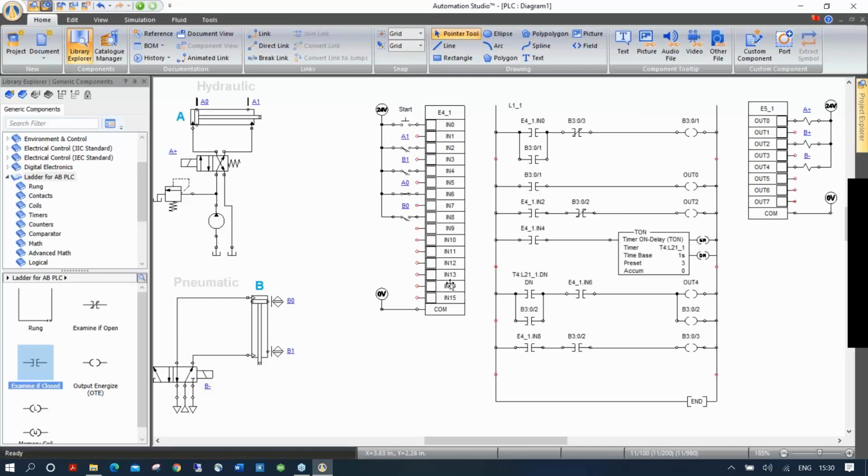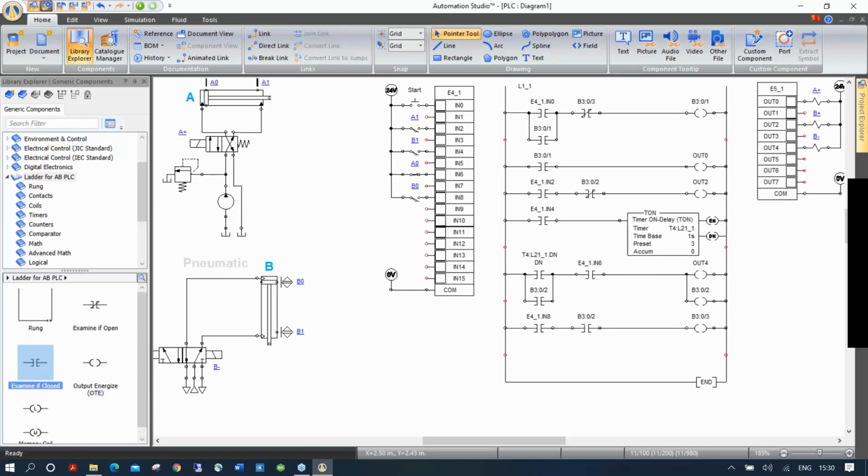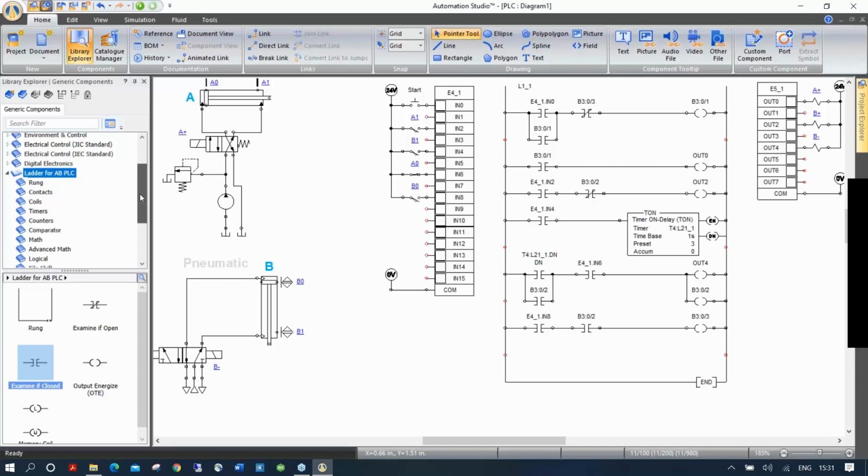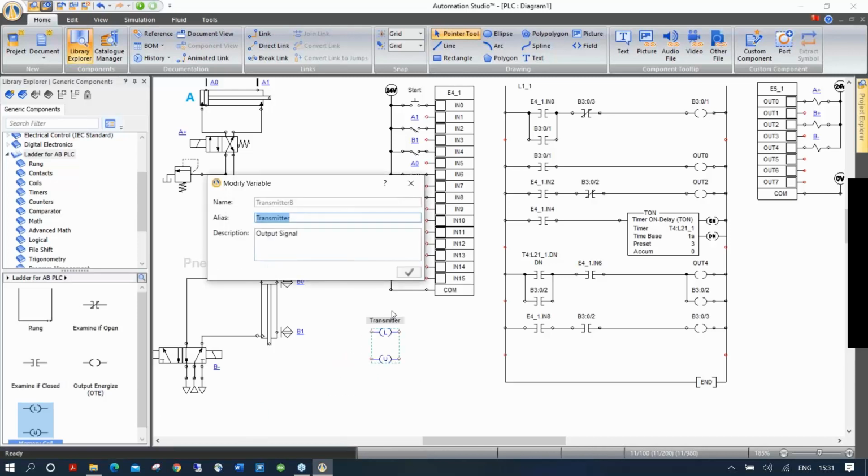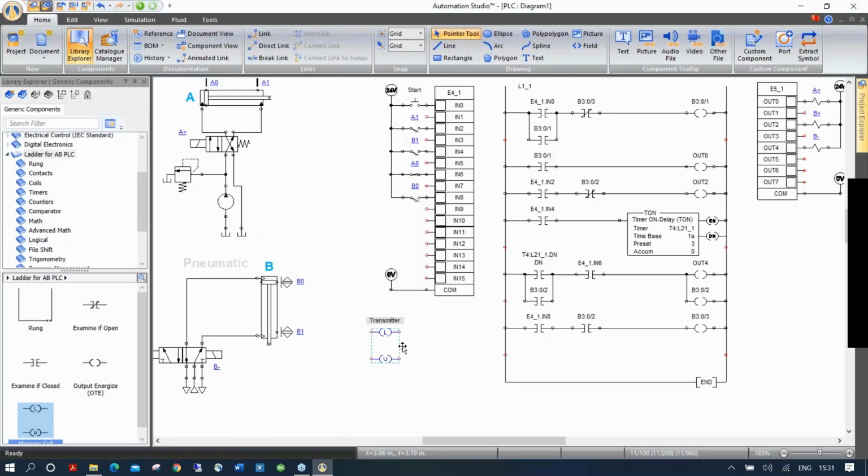Using this method, you can also, in version 7 that's coming out, I want to show you something here. We have some updates on the PLC side. By the way, this PLC that we have here has been going on for a little while. So there are some issues with it, like the latch and unlatch. They need to be connected together like that because we cannot write on the same variable in this version, okay?